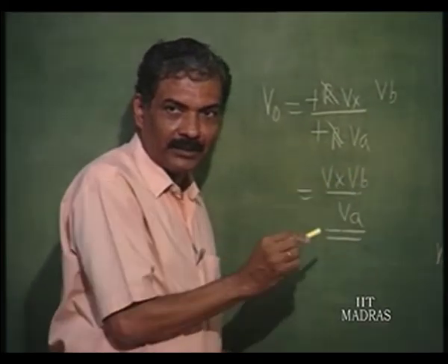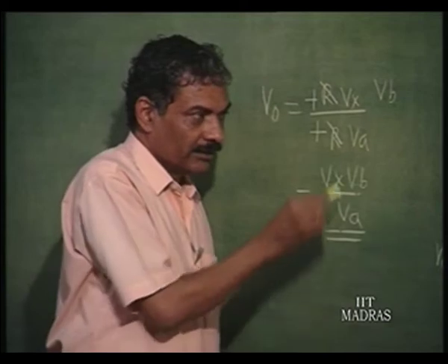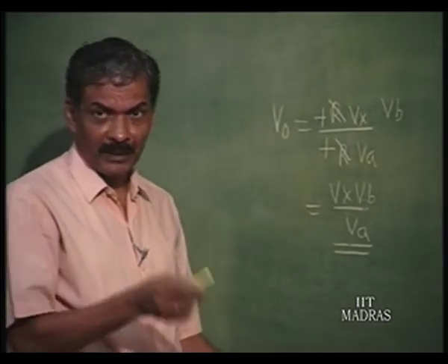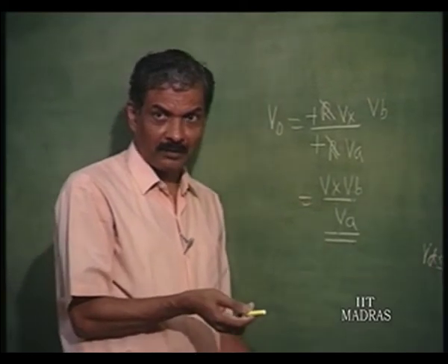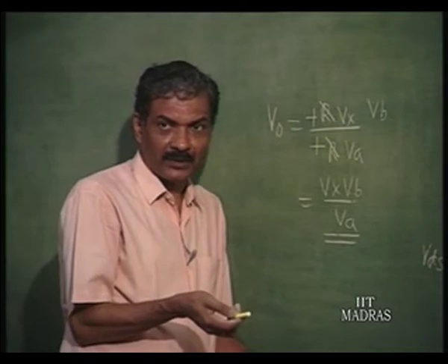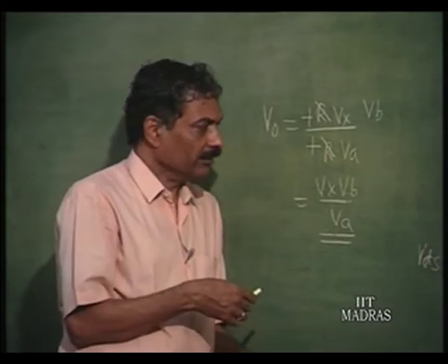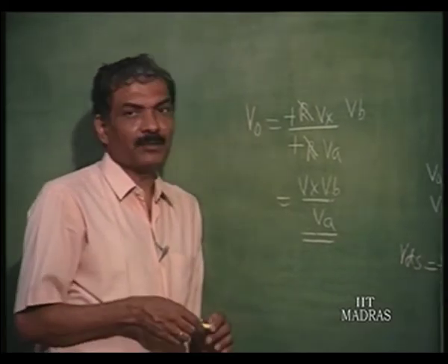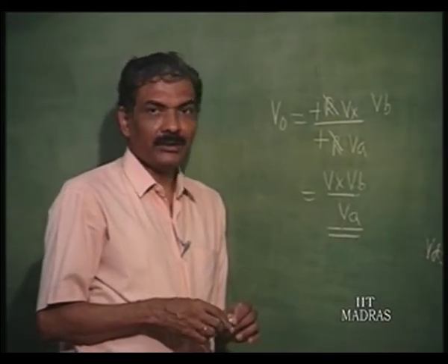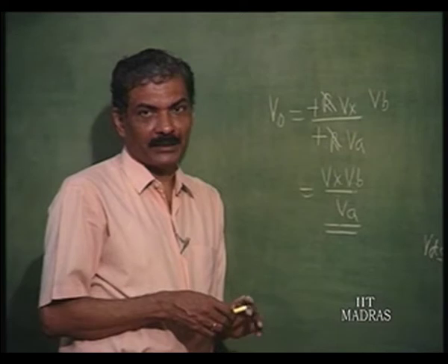That is something that you have to note. Again, if it is a 2 quadrant, it can be made a 4 quadrant by proper biasing and feed through, and then eliminating the feed through component later. So, these are the basic principles of multipliers that are used in a variety of circuit applications.